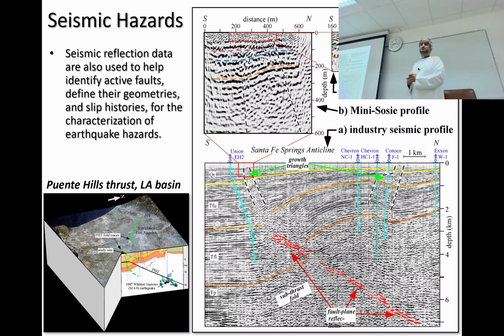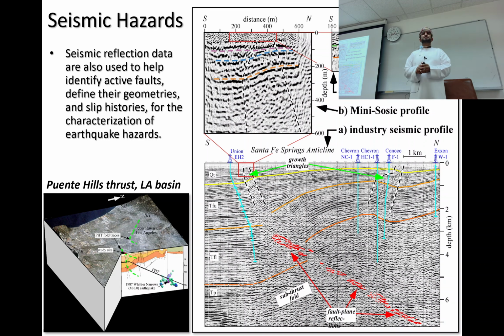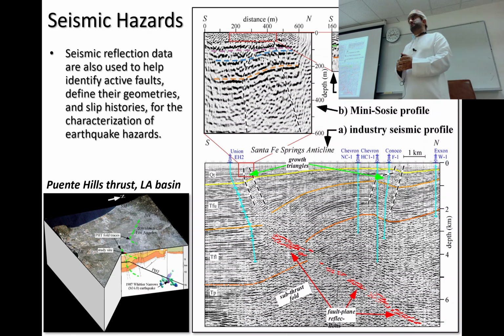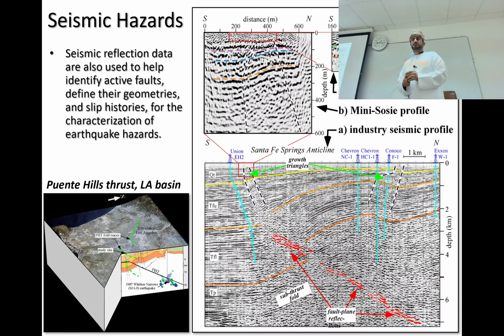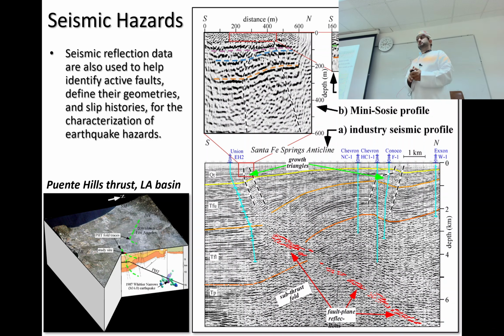In geophysics, they try to convert this data from time domain to what domain? Depth domain. This is a whole topic. Students studied it in the other course, the applied one. So don't be astonished that in the previous sections all the y-axis was time, whereas right now I'm showing them in depth domain. This is a process we apply called depth conversion, to convert the data from time domain to depth domain.